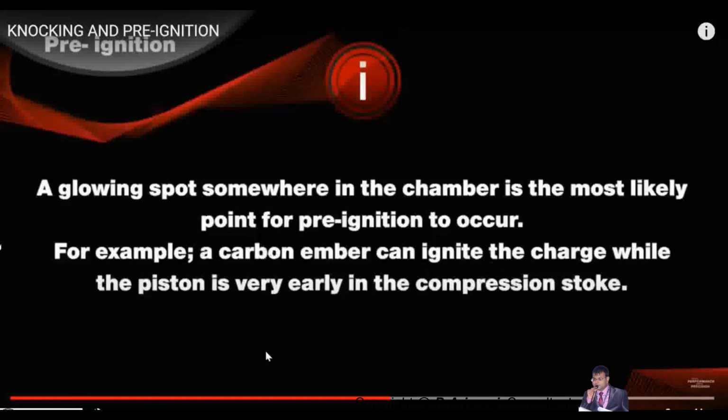And you need to ensure that you are following the timing diagram. Even the timing will vary from engine to engine and with the configuration of the engine. Even the OEMs follow different valve timing diagrams. Let's say you have some buffer. When I say 15 degrees, it is not exactly 15 degrees. You may also have 15 degrees or 20 degrees before TDC where the ignition will happen. Even in the case of a diesel engine, the same phenomenon you need to follow.